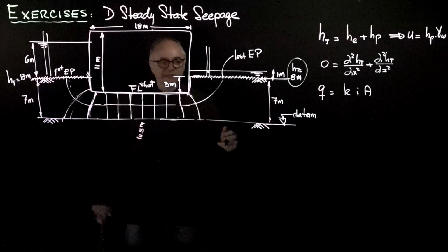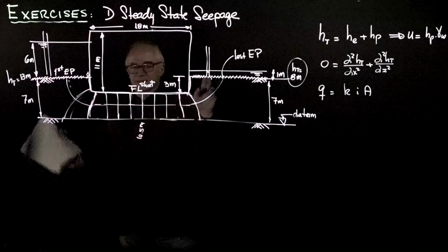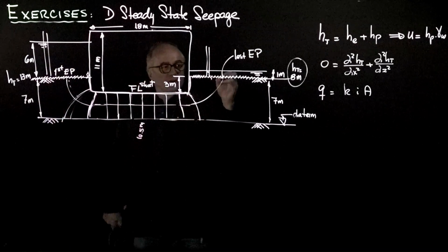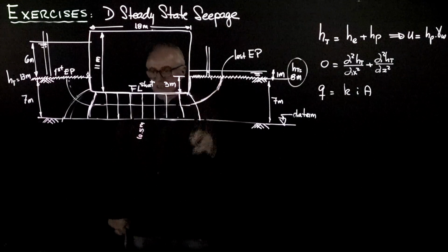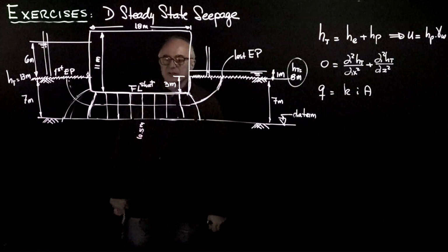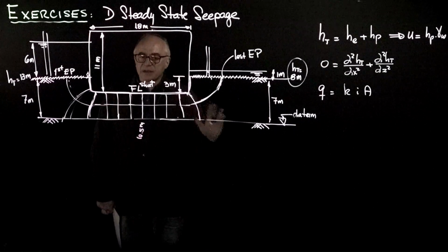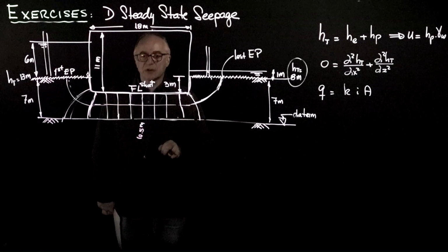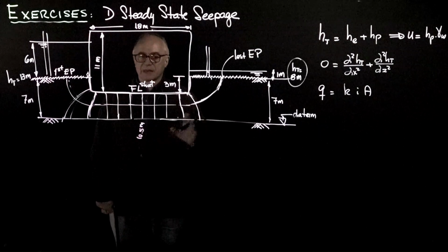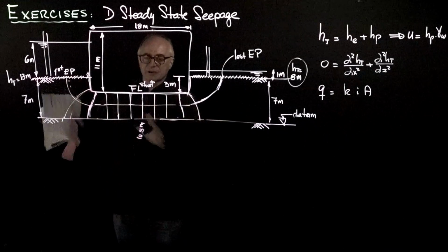This would be a first iteration, and you can identify lots of failures to satisfy this concept of squareness or normality in this case. So please correct in successive iterations. But it is good to get started. And for the rest, please follow the guidelines in the previous video on how to solve a flow net. But the most important step, regardless of the solution, was to get the boundary conditions.